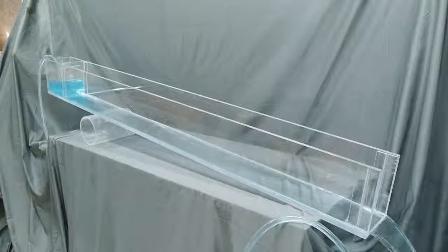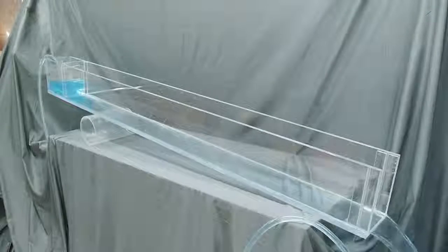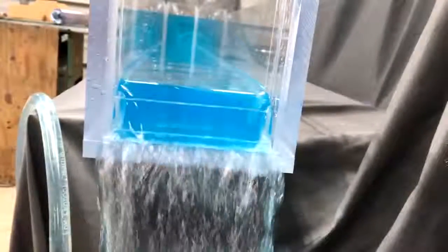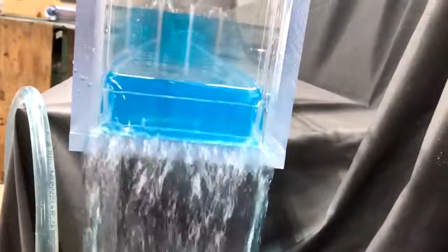Fast-moving flow is called supercritical. In this case, the flow velocity is faster than the wave speed. You can see that the waves aren't able to propagate upstream. Supercritical flow is controlled on the upstream side, so nothing I do downstream affects the depth of the supercritical flow above. A flow profile can naturally transition from subcritical to supercritical.